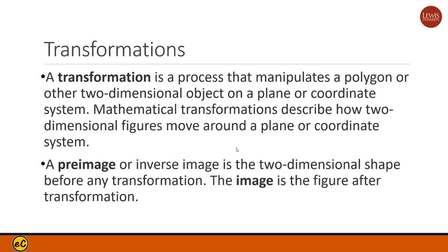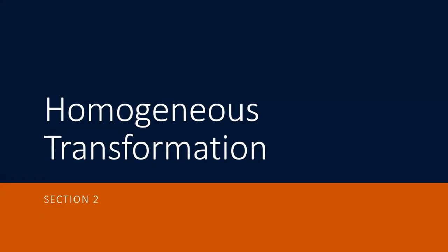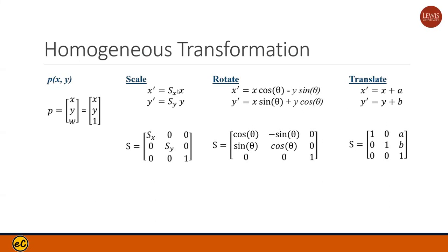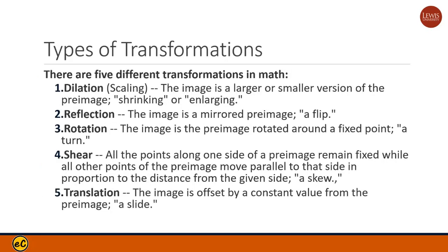It just becomes a rotational matrix. Everything becomes so. Using this homogeneous transformation, you can combine translation, rotation, orientation, and even scaling together in one same matrix operation. Then you go back to chapter 1. We talk about linear algebra, right? The appendix that we did in week 1. You put everything into Python and you would be able to calculate. That's the whole purpose of this discussion. This is a homogeneous transformation. That's the whole purpose of doing that.